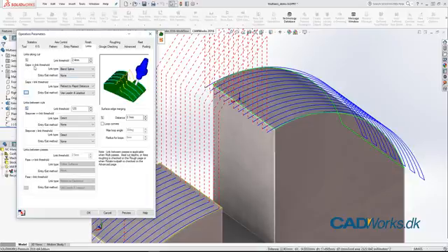So if you are in the small gap, you use one entry and retract. If you are in the large gap, you are using a different lead in, lead out. And the same between regions, or between cuts, you can have individual lead in and lead out motion. This is a bit beyond the scope of this video. So now you know, now we don't care anymore.